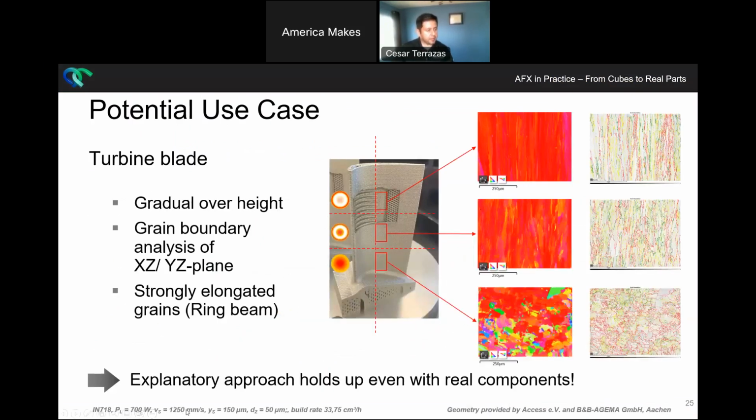They started with the baseline like this, so they had 700 watts of power and a specific speed. The only thing that changed between these and the 2 emission modes was really the spot. They kept consistent layer thicknesses, power, and velocity, which are the standard parameter settings. Did that answer the question?